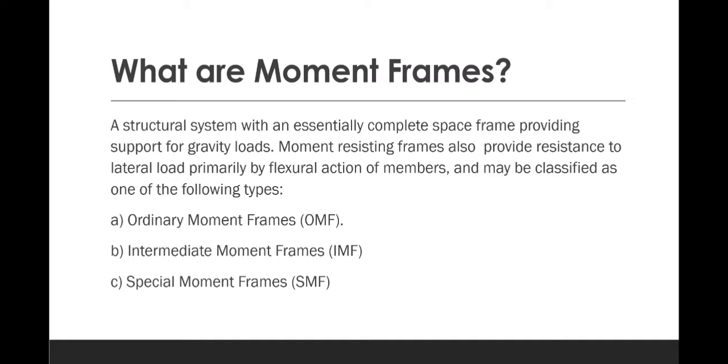What are moment frames? A structural system with an essentially complete space frame providing support for gravity loads. Moment-resisting frames also provide resistance to lateral load, primarily by flexure action of members, which are the beams and columns, and may be classified as one of the following types. First is the ordinary moment frames, second is the intermediate moment frames, and lastly is the special moment